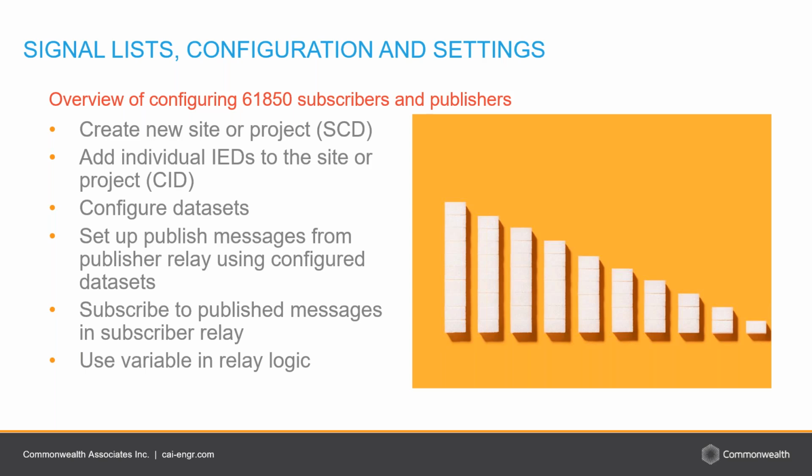And you have each relay with the breaker closest to the rail publishing information about breaker failure initiate and maybe even breaker failure trip. And typically that is passed to the bus differential relay because it's already going to be tripping a lot of those relays or a lot of those breakers anyway. So that could be one way to group these published messages and to have your subscriber relay subscribe to that information.